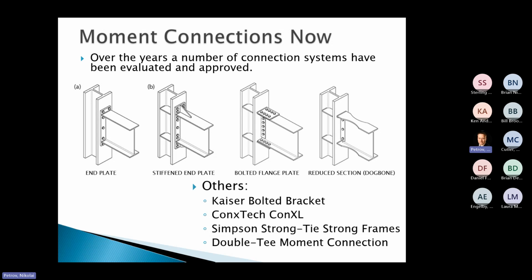Here you've got a stiffener that gets in the way. Here you've got this entire flange plate that gets in the way. So if you've got a floor or a roof, it's a little easier to deal with the roof. You support the deck around the connection, and then all the stuff that's happening up on top gets lost in the insulation, and that's not that big of a deal.